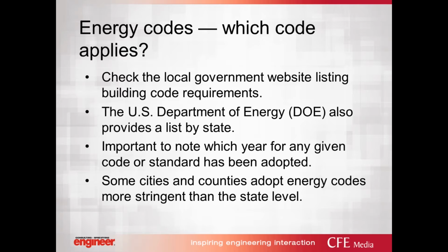There's also the U.S. Department of Energy, which has a website, energycodes.gov, that you'll be able to access with the slides from the previous slides. When you go to that website, you can pick what state you're in, and it will tell you the energy codes that apply. And there's also a link to download the ComCheck and ResCheck. Those are the compliance forms that you would use to show that you're complying with the energy codes.